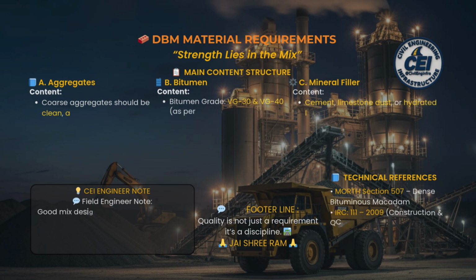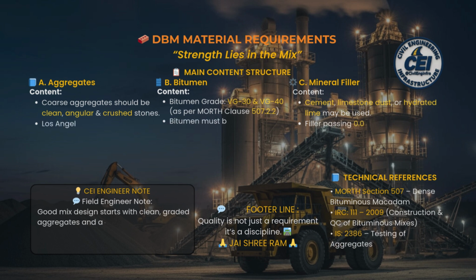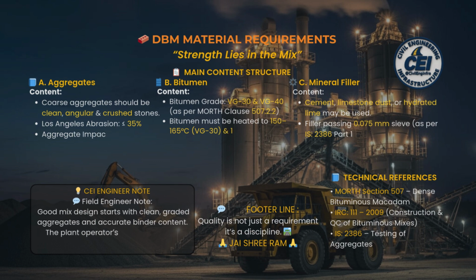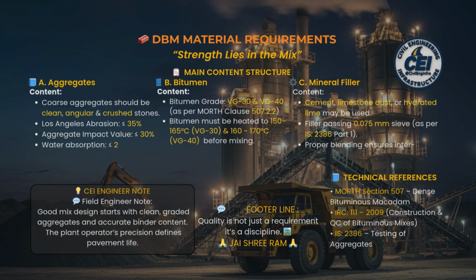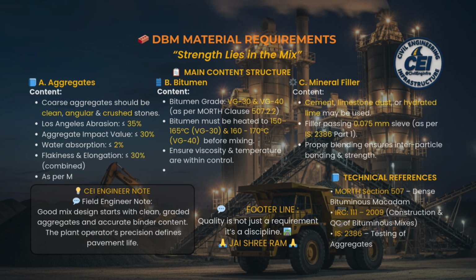Strength lies in the mix. The durability and lifespan of a road depend entirely on how accurate and balanced your mix is. A. Aggregates. Aggregates form the skeleton of DBM. They must be clean, angular, and crushed stones. Los Angeles abrasion less than or equal to 35%.